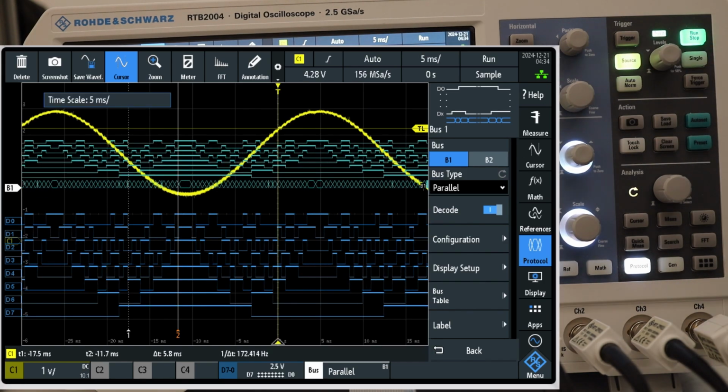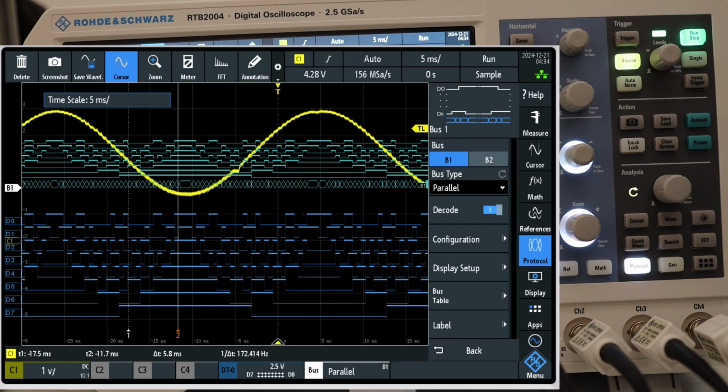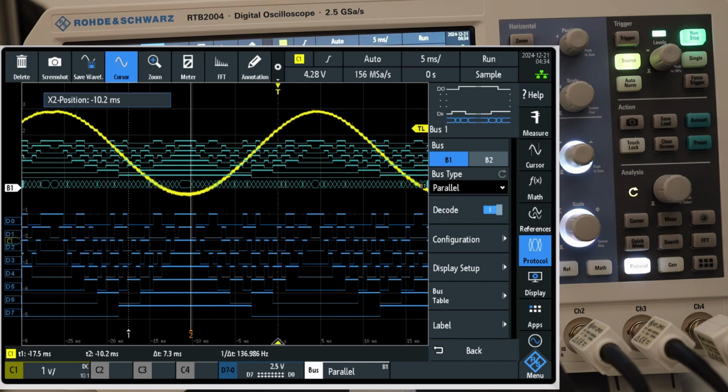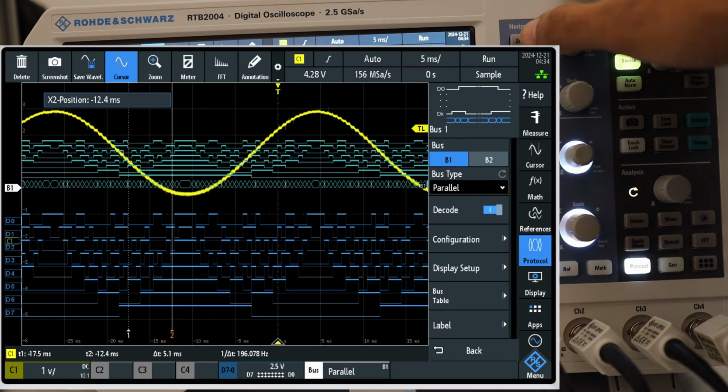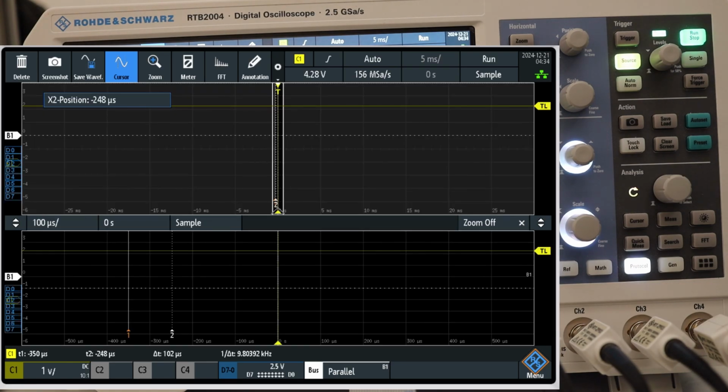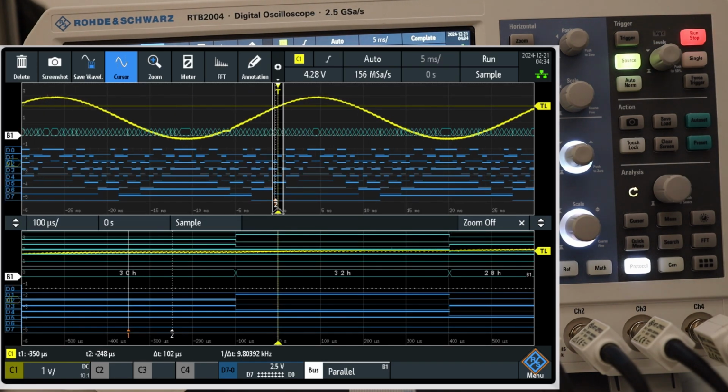You see this oscilloscope shows you two views of the logic. One view which got captured and another view which the bus decoder understands. This helps you to determine that you are not setting the incorrect threshold and stuff like that. Remember, we found the threshold to be 5 volts and we set it in the middle of it, and let's look at it.